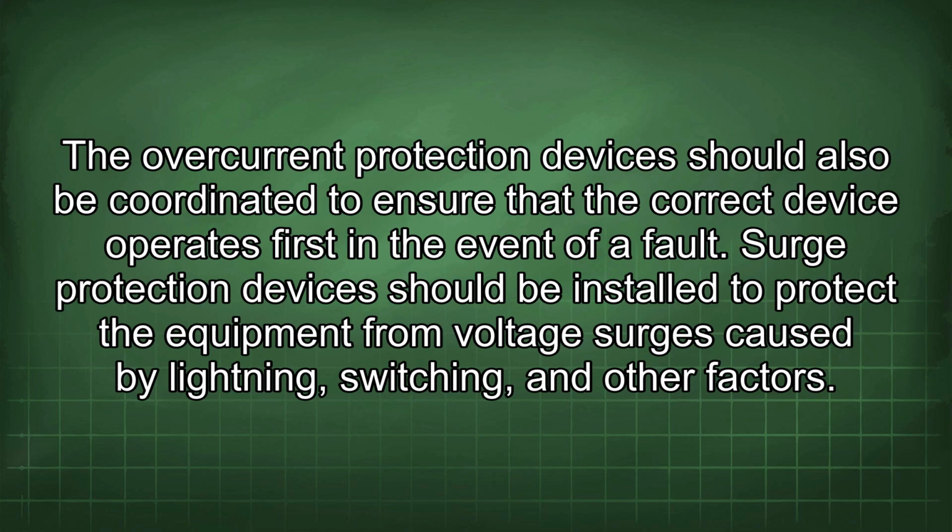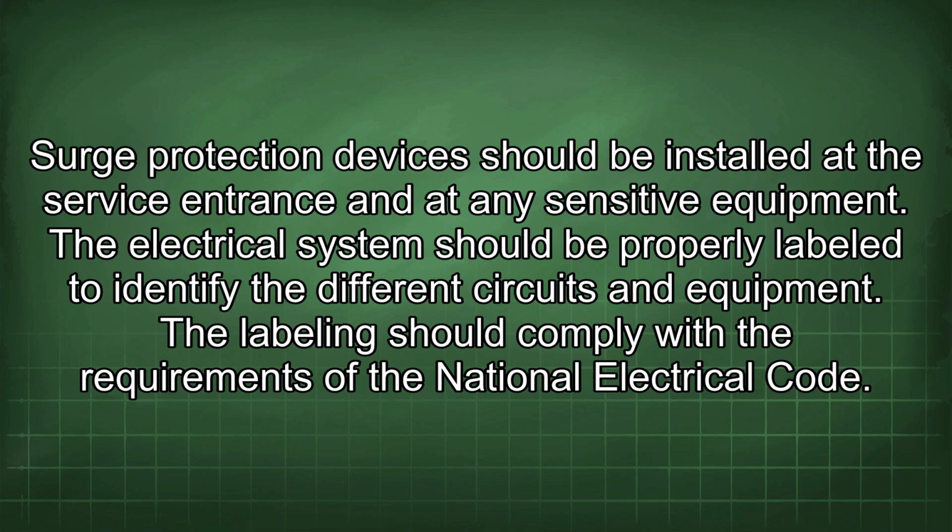Surge protection devices should be installed to protect the equipment from voltage surges caused by lightning, switching, and other factors. Surge protection devices should be installed at the service entrance and at any sensitive equipment. The electrical system should be properly labeled to identify the different circuits and equipment. The labeling should comply with the requirements of the National Electrical Code.